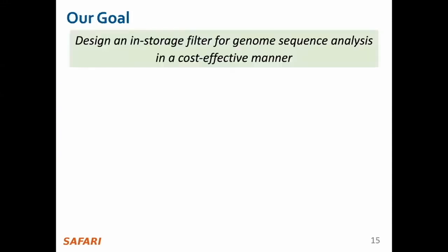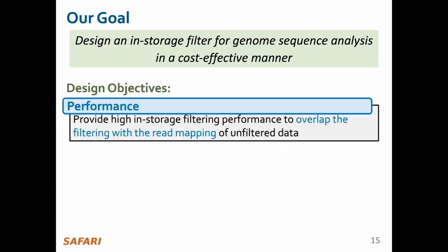Based on these observations and motivated by these studies, our goal is to design a storage filter for genome sequence analysis in a cost-effective manner. To do that, we have three key design objectives in mind. First is to provide high performance of storage filtering by overlapping the filter process in the SSD with the read mapping of unfiltered data. So we want to send the unfiltered data to the system that performs read mapping meanwhile we are performing filtering inside the SSD.